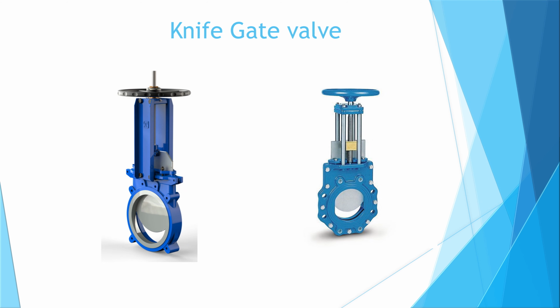Knife gate valves are another type of gate valve. They are characterized by their extremely thin profiles and their knife-like gates. Knife gate valves are most likely the thinnest type of valve that you can get. Knife gate valves are typically used in applications where a thin profile is very important, and they are sometimes used in applications with highly viscous fluids that need to be cut in order to be isolated.